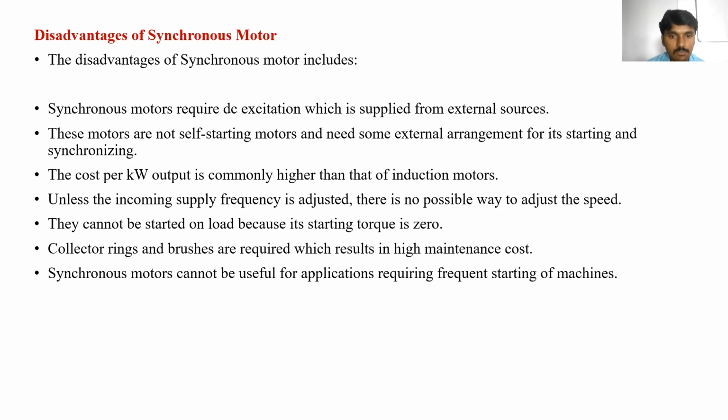Collector rings and brushes are required, which results in high maintenance cost. Synchronous motors are also not useful for applications requiring frequent starting. Okay, this point should be modified. Here also, like commutators, we are using collector rings and brushes in the synchronous motor for giving the DC supply to the rotor circuit. Due to this, some maintenance is needed.